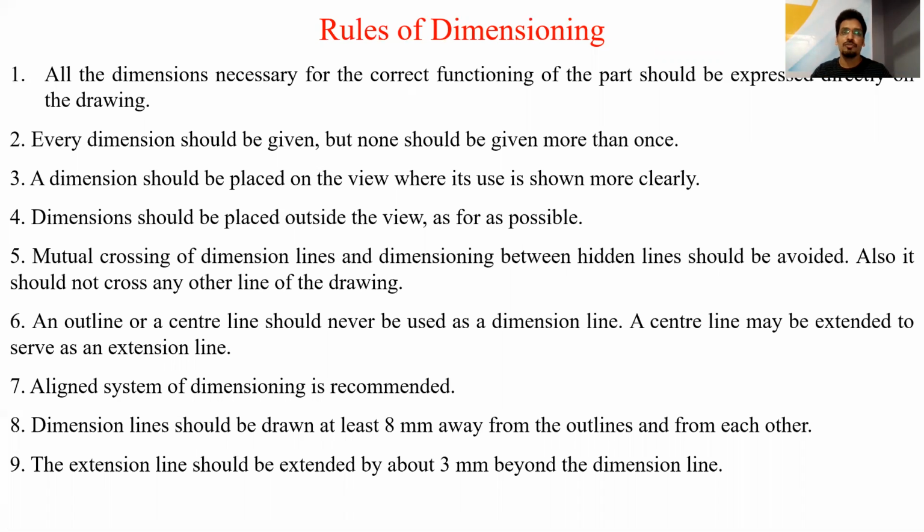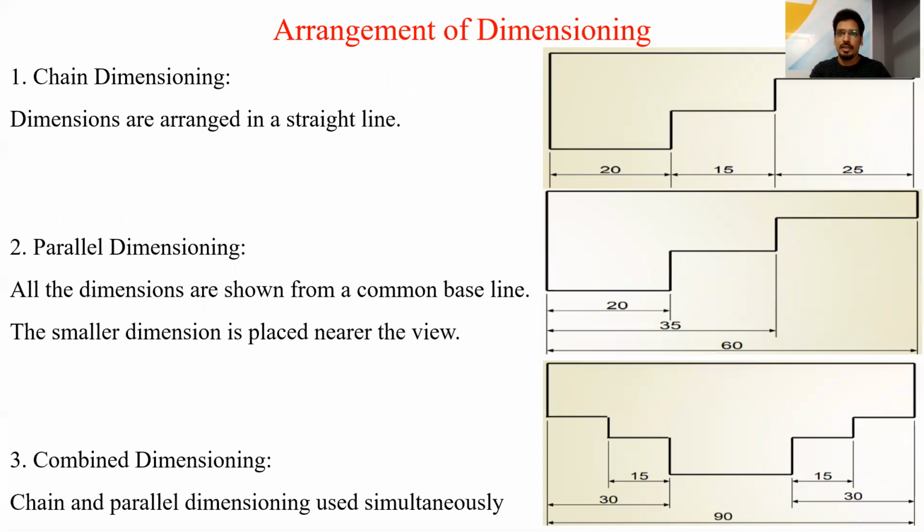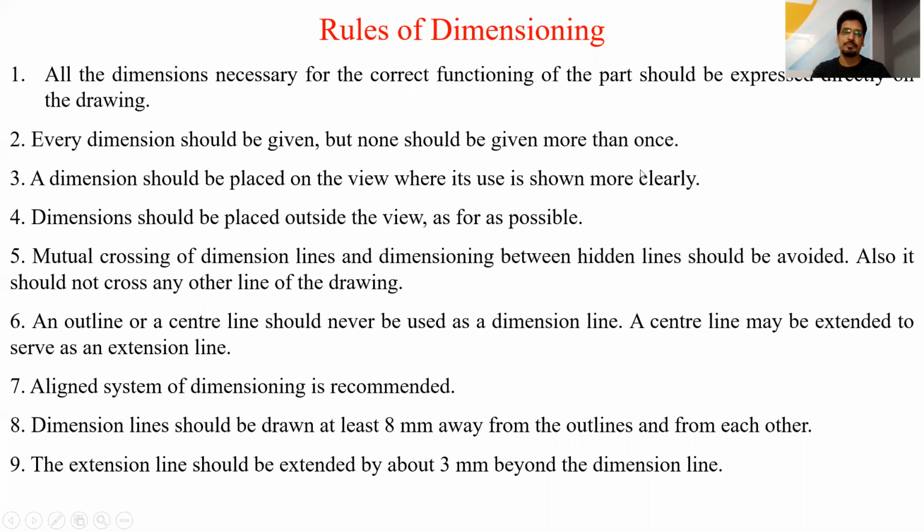Next, dimension should be placed outside the view as far as possible. This is very clear that in the previous figure, there is no dimension in the drawing sheet. The dimension is out of the view. Dimension is not written inside the figure. It must be outside the figure.